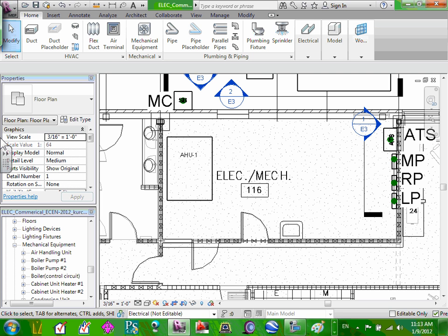Before we circuit it, I want you guys to continue reading on it. It says Division 16 to provide variable frequency drive, VFD unit. Oops, we need to provide a VFD unit for this baby. Not enough just an air handling unit. They're saying Division 16, aka electrical, is to provide a VFD. So I need to find a VFD unit and throw it on the wall so I can control it. Otherwise, if it doesn't say that, I'm done.